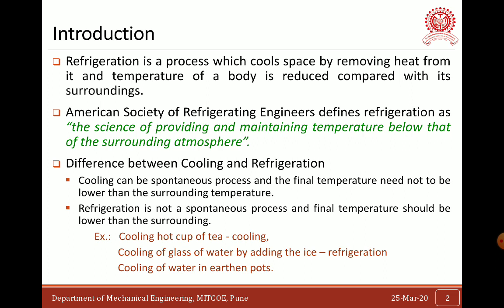Now, what is the difference between cooling and refrigeration? Cooling can be a spontaneous process and the final temperature need not be lower than the surrounding atmospheric temperature. Whereas refrigeration is not a spontaneous process. It is cooling some space or some object, and the final temperature should be lower than the surrounding. So we maintain the temperature below the surrounding in the case of refrigeration.